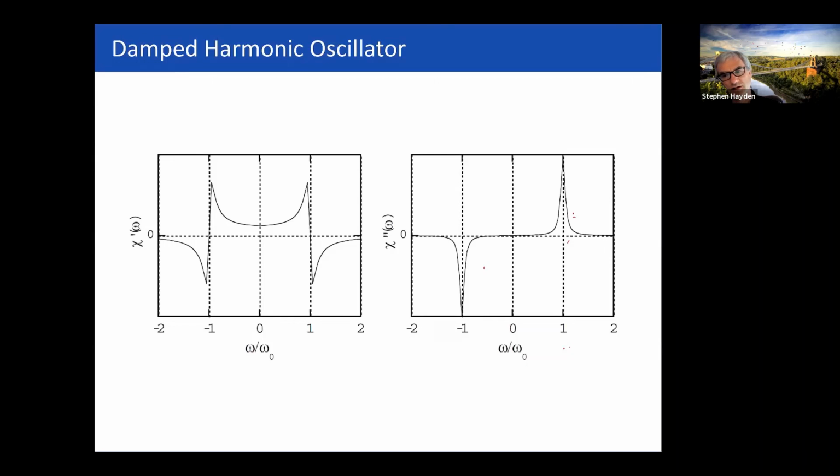Okay, and then if you only have one type of excitation, and you come up to the resonant frequency, then you get this funny behavior where it flips from going up. That's corresponding to the phase of the response changing, right? So when you're at the resonant frequency, the response will be 90 degrees out of phase with the applied force, and so you get maximum absorption.